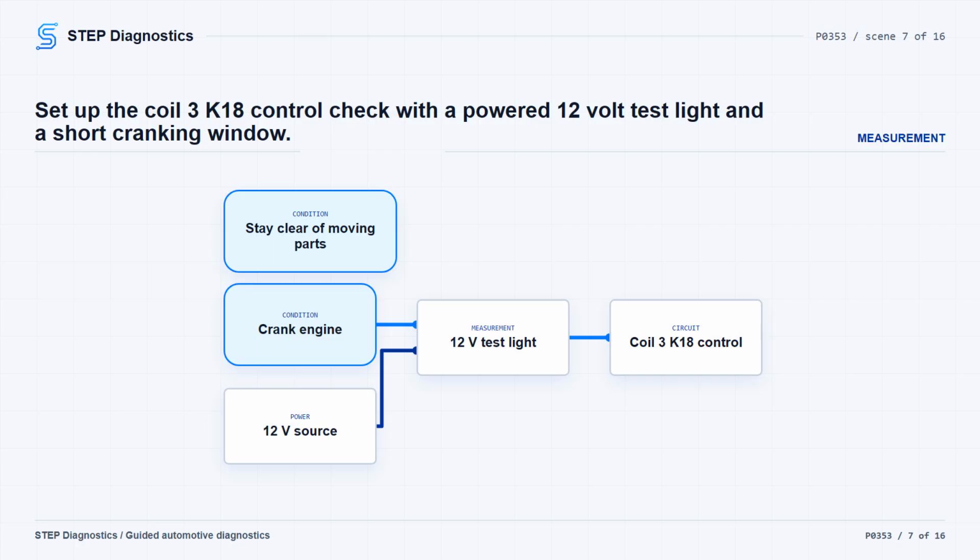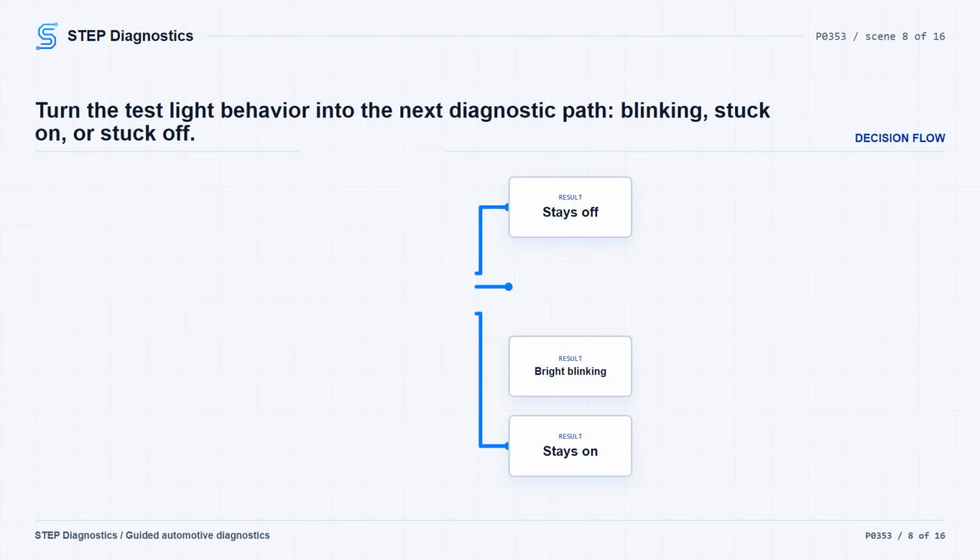Stay clear of the fan, pulleys, belts, and any moving parts while cranking or running the engine, and do not wear loose clothing.